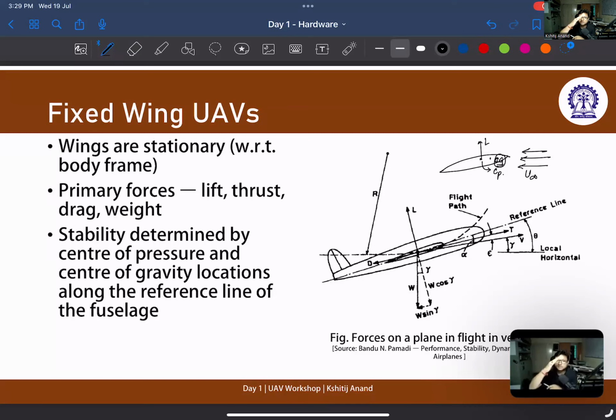After a certain angle of attack, the aircraft is simply going to lose lift and fall down. So we want to apply force to keep it nose up in a certain position, and then when we release our controls, the aircraft should have a natural tendency to come back down.